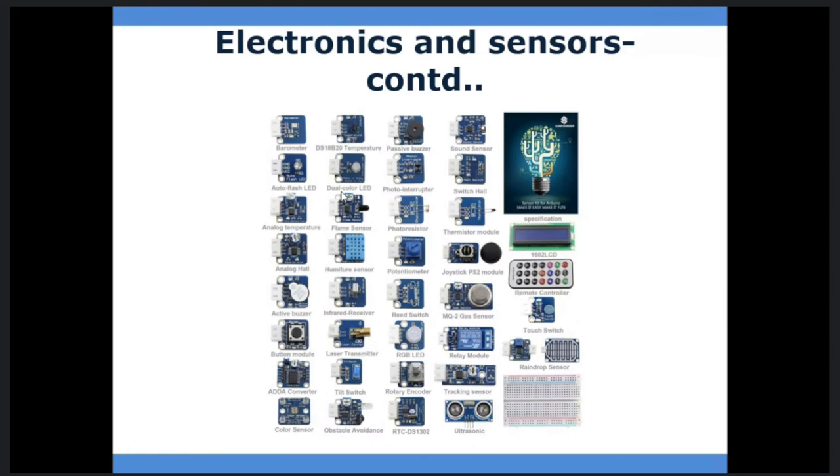And these are again temperature, barometer, sound sensor, hall effect sensor. It's a magnetic sensor. All the sensors work with unique applications, with a unique concept. Either an electromagnetic field, for example, when you consider the inductive proximity sensor, it works with electromagnetic field changes. When you see the passive infrared sensor, it works with the concept of changes in temperature. The ultrasonic sensor works with the delay in getting the signals, pulses, time period. And the IR sensor, infrared sensor, works with delay or missing of infrared signals.